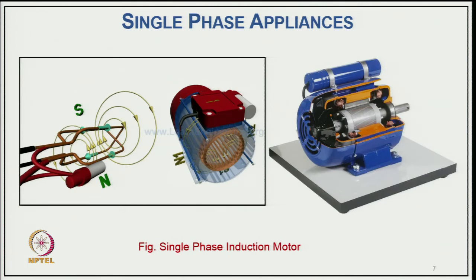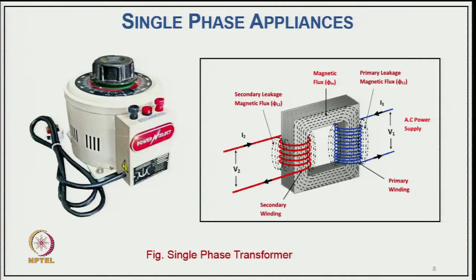Well, you have other single phase appliances, typically like the single phase induction motor, which are huge in number, starting from a very fractional kilowatt rating to some kilowatt rating, maybe having different kinds of starting methods. Most of the applications with a small power rating, in fractional kilowatt, use single phase motors, whether it is the compressor motor, a fan motor, other appliances, or a small pump application, typically less than 1 kilowatt or so. We call it fractional kilowatt. Most of them are single phase induction motors.